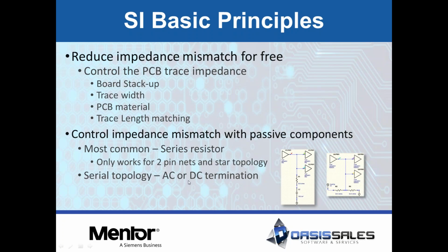When you have a multi-drop net configuration, you may have to put a resistor capacitor at the end of it to help control reflections. It just changes, again, that impedance at the end of the line, so you're not getting the reflections as bad in the end. The whole idea of the passive components is you're just trying to match the impedance from the driver to the receiver. When you have a series resistor, and your resistor at the receiver that goes to ground, you have a voltage divider. So you have a basic impedance matching circuit at that point.